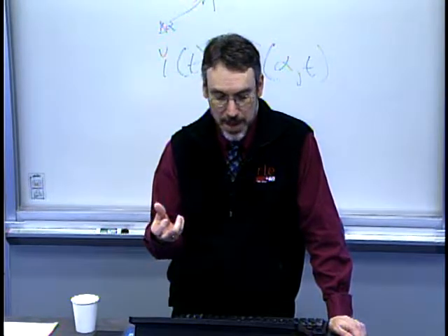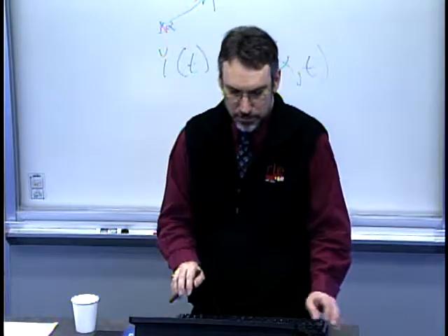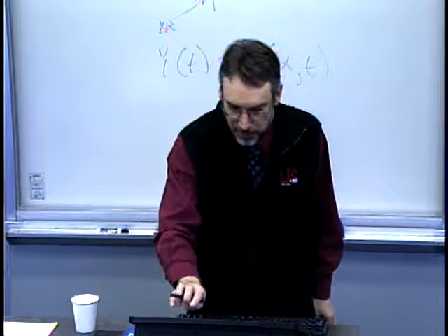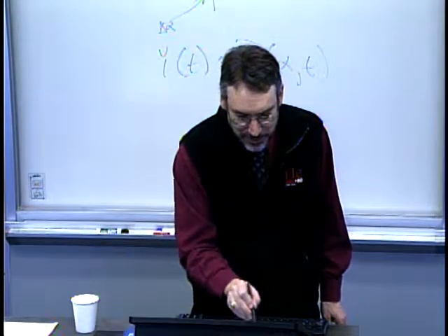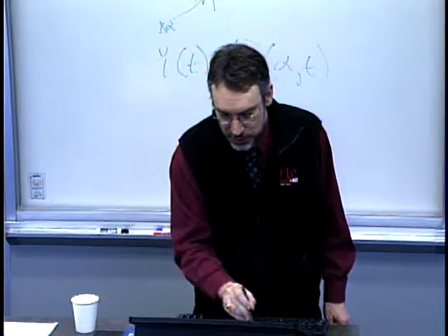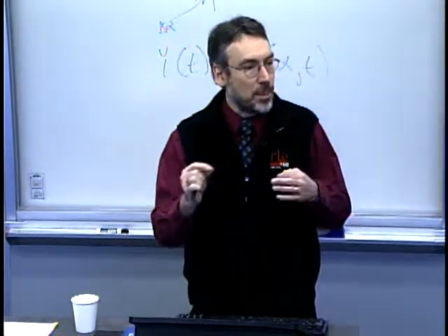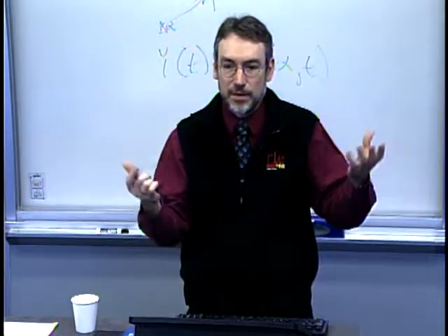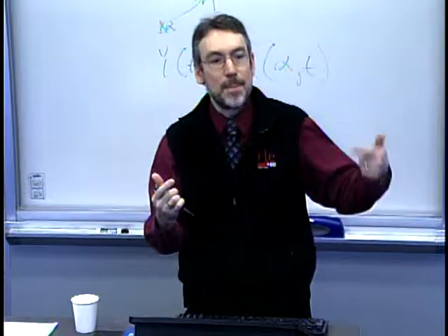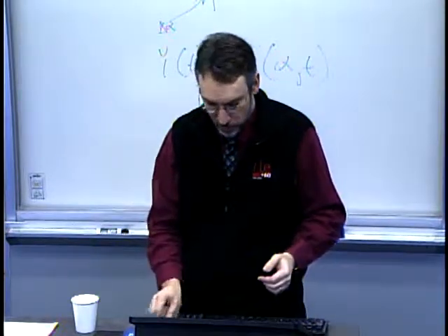And then the other thing here is, in here we were basically having a similar band, and it was all just kind of shifting. But the part-to-part variation did not seem to change. The variance of the process did not seem to change. The mean shifted. So that's a very common characteristic that we're worried about.